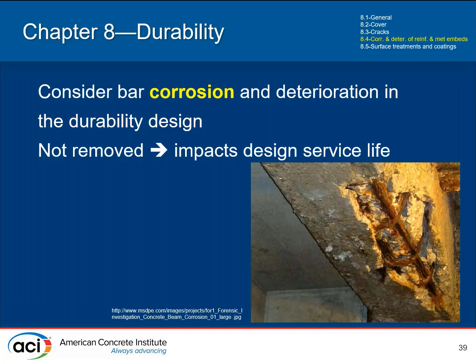It is trying to be a practical document that people can use, and doesn't put you in boxes that you can't get out of, but it does want you to consider that if you can't remove the corrosion product on your steel for whatever reason, it will have an impact on your design service life. You need to evaluate that and try to overcome it in another way.